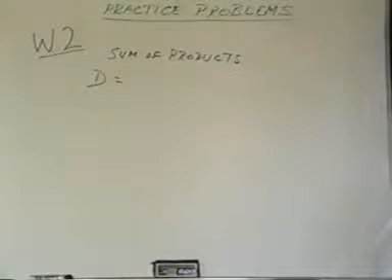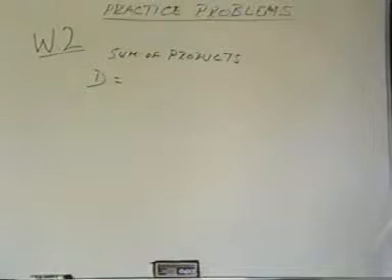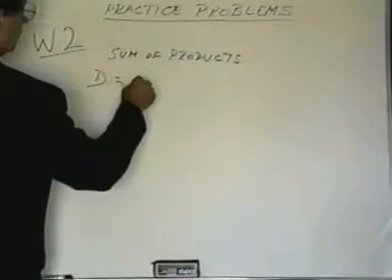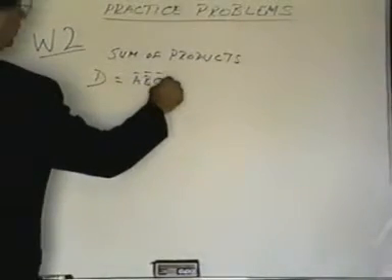For problem number 2, we'd like to obtain the sum of products and the product of sums expressions for D. Well, the sum of products is easiest. The table we had on the board a minute ago, there were 6 minterms present. And those 6 minterms, as you may recall, were the very first 6. Only the last 2 were zeros. That means I can write this out in longhand form this way. It's A naught, B naught, C naught. That's the very first row.